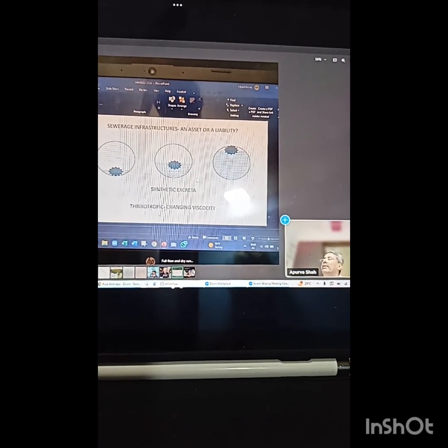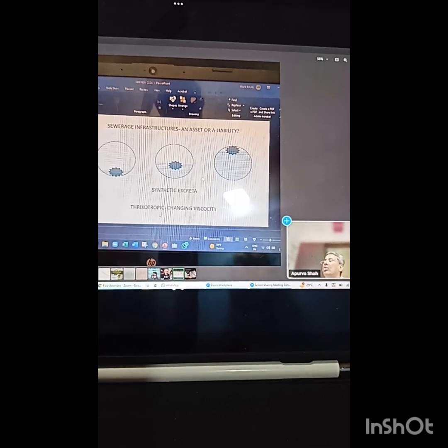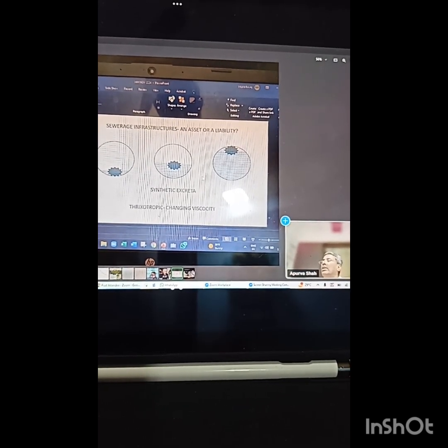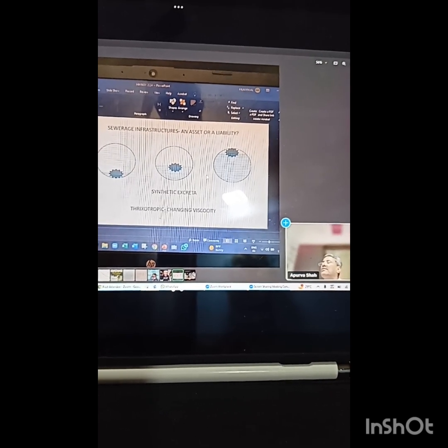Yeah, so these are the principles on which basic pipe diameter selection is done. And for black water, where solids are there, this is very important. Grey water, normally solids are not there, but floating particles are much more. Kitchen waste also has solid particles.